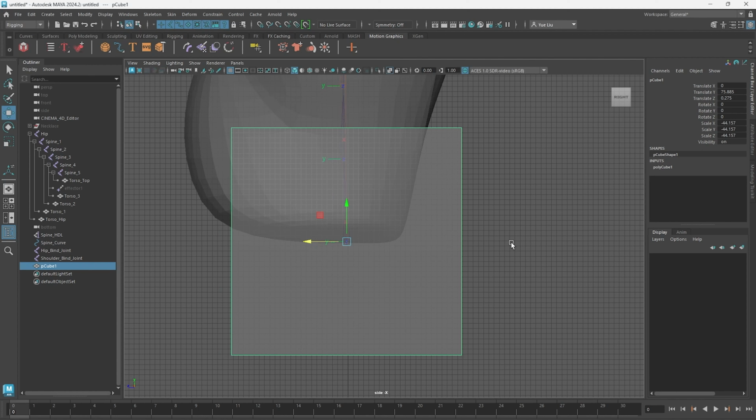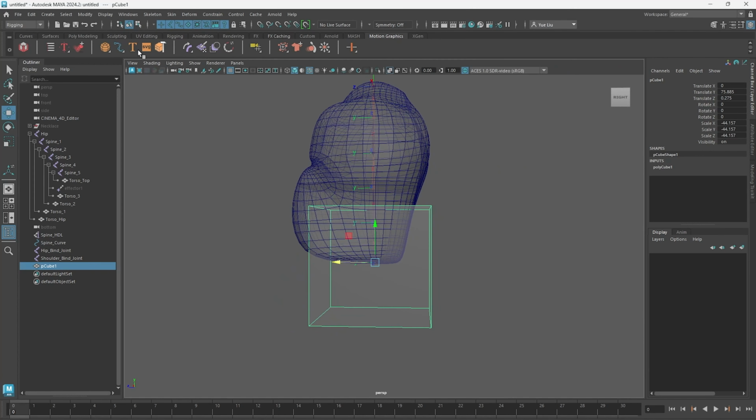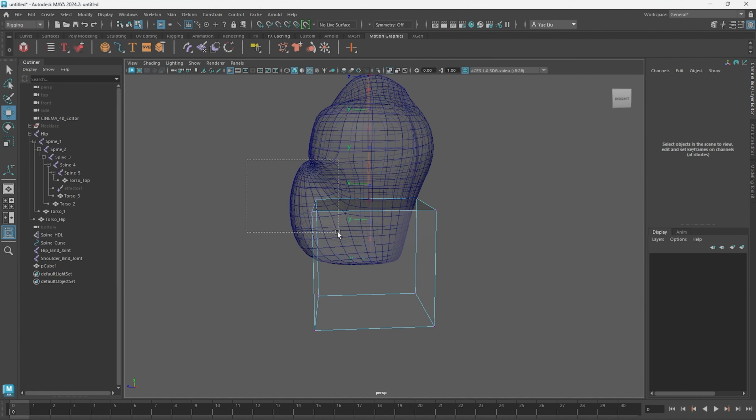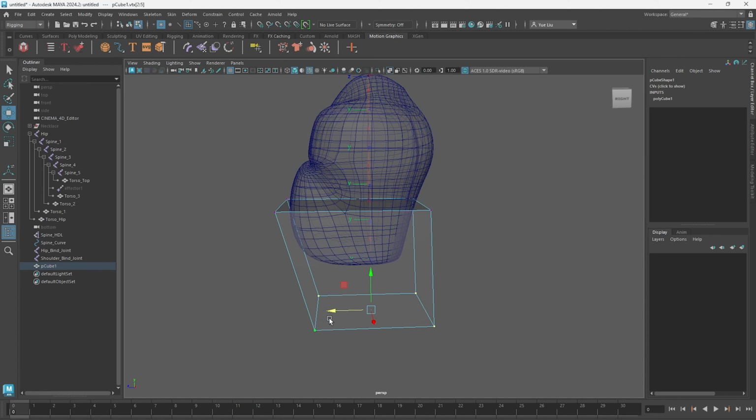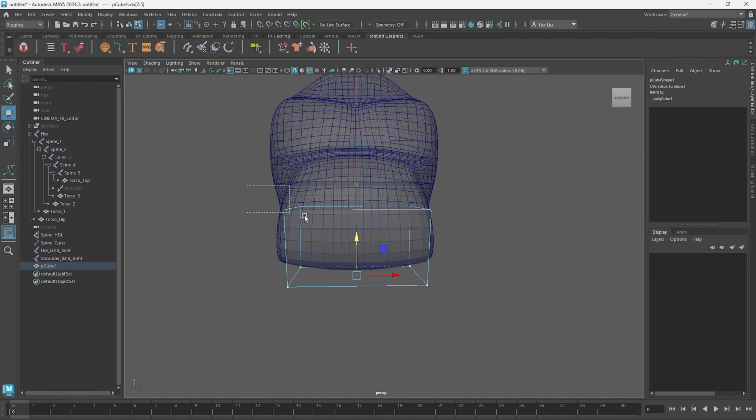And then I'm going to modify this curved shape to kind of look like how I want my controller to be. So I'm going to move the CVs out, and position them to some place that I can kind of use to control from. So outside of the geometry slightly.